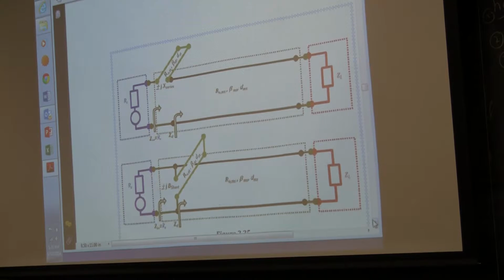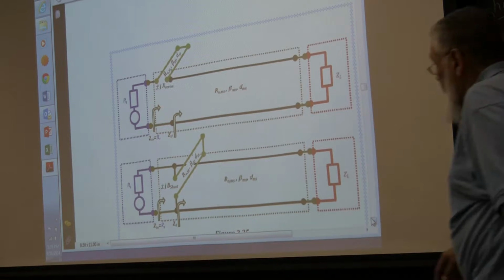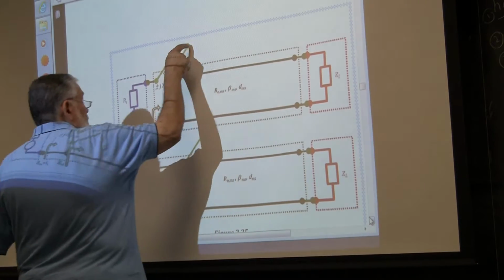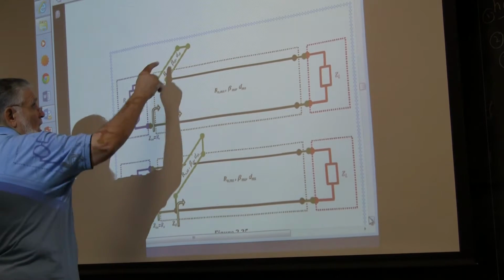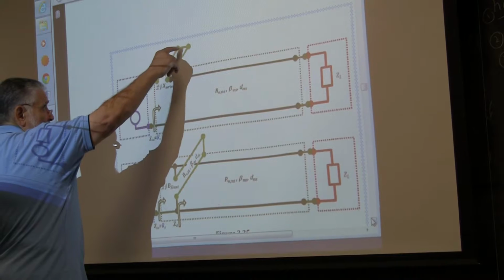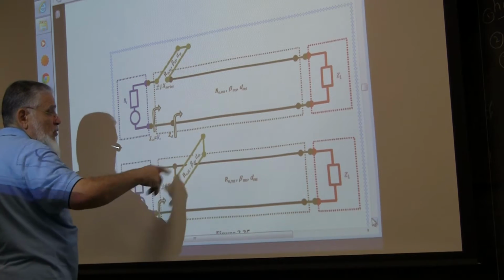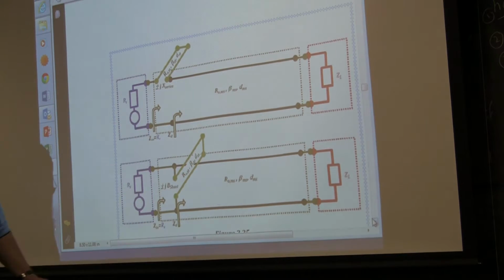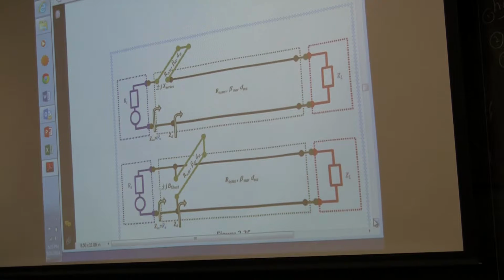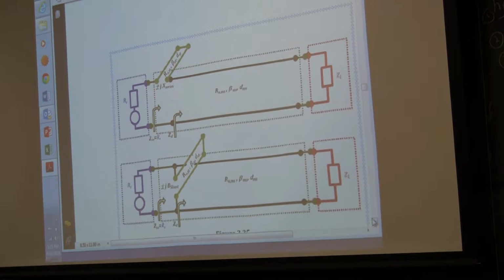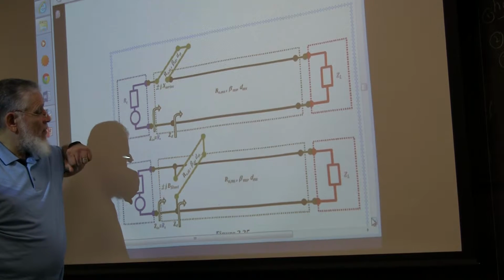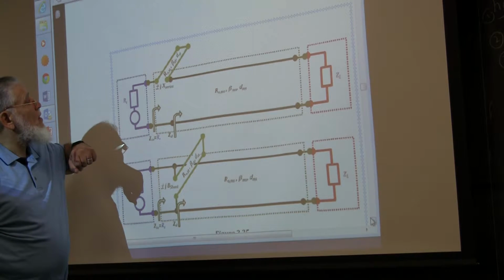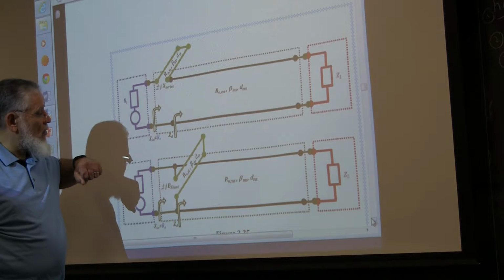So that's how we do it. That piece of reactance came from another transmission line here, and that reactance also came from a transmission line. And you notice I'm using a short circuit line, all right? I'm not using an open circuit. Although you can use an open in principle, mathematically, in the physical world we indicated that a shorted line is more practical in realization than the open circuit line.